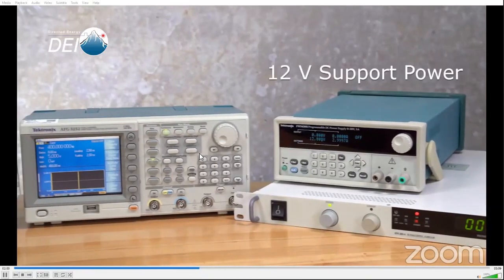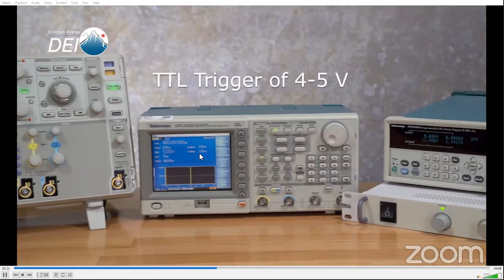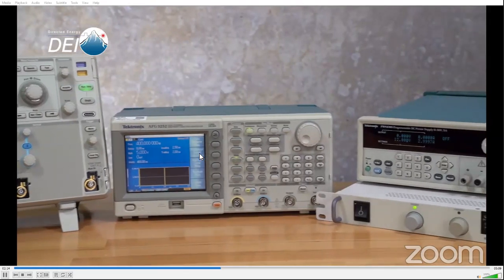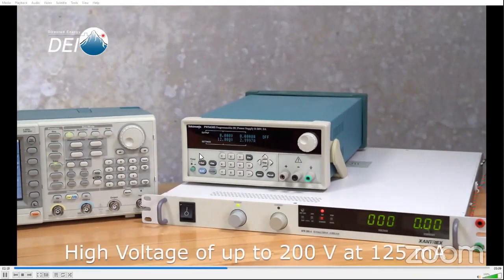While supplying the necessary power and signals is easy when designing the module into your final system, when you want to operate it on the bench for research or testing, you'll need a few things. The PCO-7125 requires 12 volts for housekeeping power. This can be a very simple and low current power supply around 100 milliamps. In order to trigger the module, you'll need a standard TTL level signal of 4 to 5 volts. The high voltage power required to operate the laser diode should be capable of delivering 200 volts at 125 milliamps.